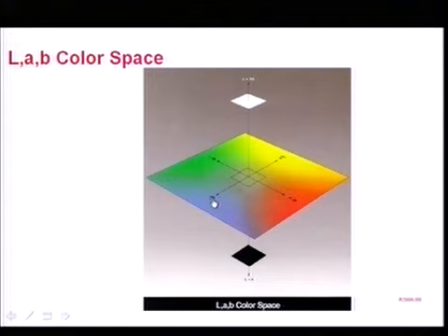Now, the goal of de-inking and bleaching process is to get to the center, make the color as close as 0, A or B value. You do not want to move to negative, because what you are doing is, from pink color or red color, you are going to make the color to green if you move to negative. You want to go to the center and go as high as possible to make white color paper.